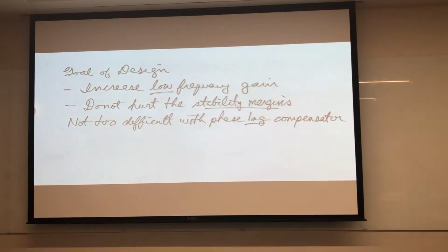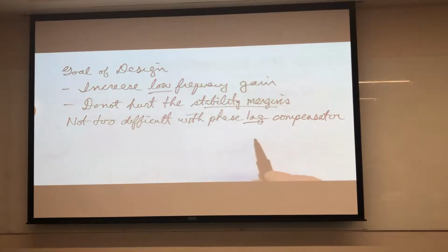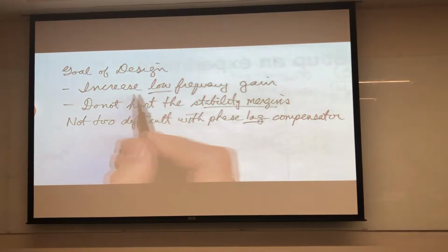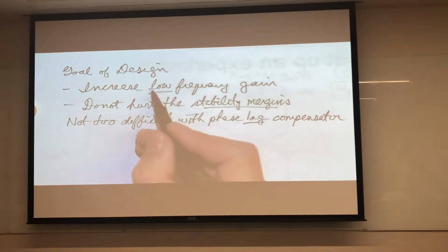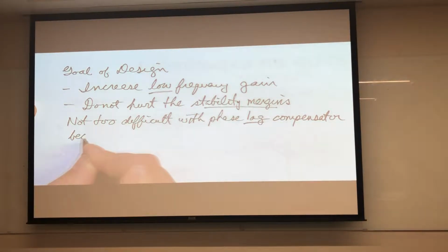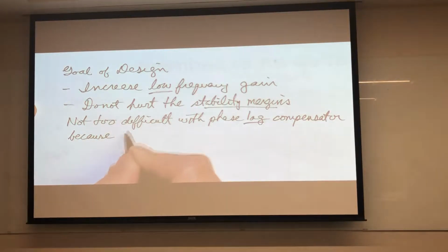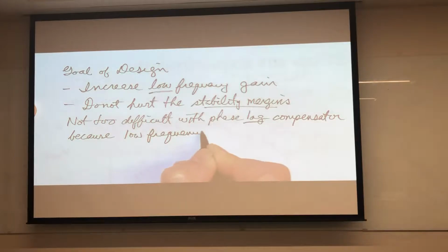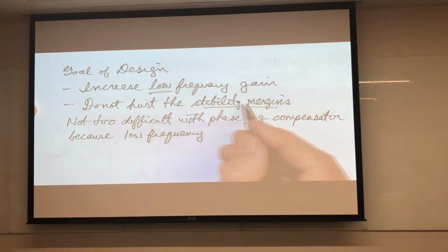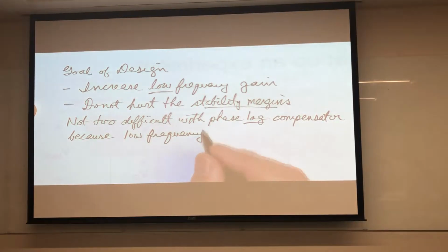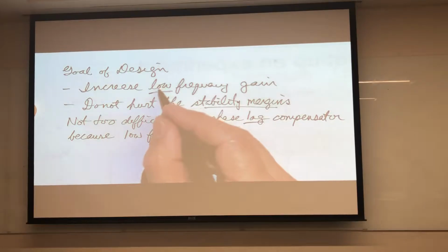The reason it's not too difficult with a phase lag compensator is because one of the characteristics that we desire is occurring at low frequency. We want to increase the low frequency gain, but we don't want to hurt the stability margins. So it's not too difficult to design this because we have a separation between low and high.